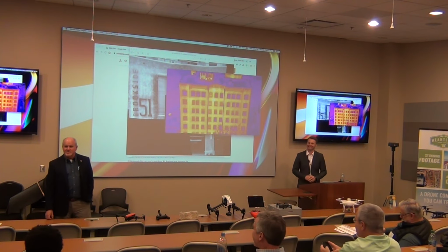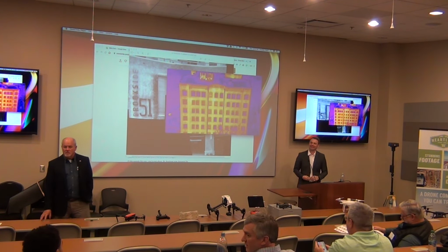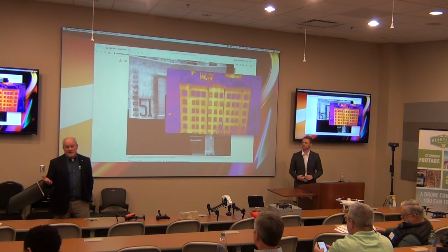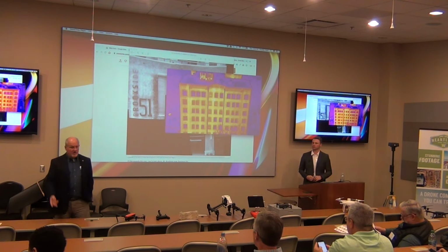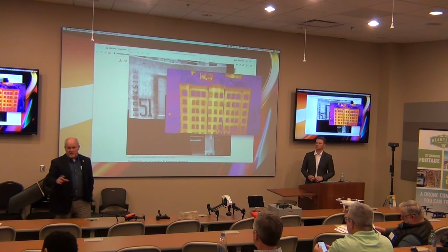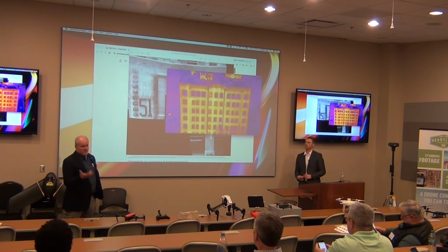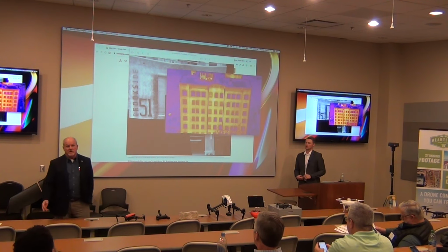And you can look at a roof with an RGB photo and it goes, yeah, it looks good, until you see that water sitting underneath it with the thermal. That's right. The RGB photo would have told me, in fact, it did tell me it's a relatively new roof, modern technology, heat welded seams, PVC, single ply. They had the treads put down for wear areas. It looked proper. Right. But once we got up there with the thermal camera, it was just lit up like a Christmas tree in several areas.